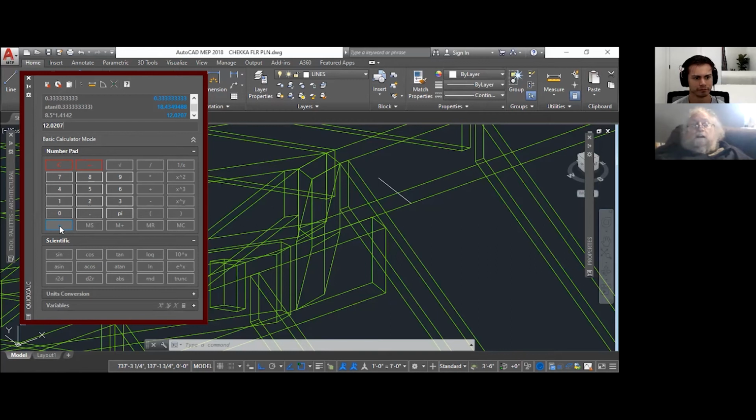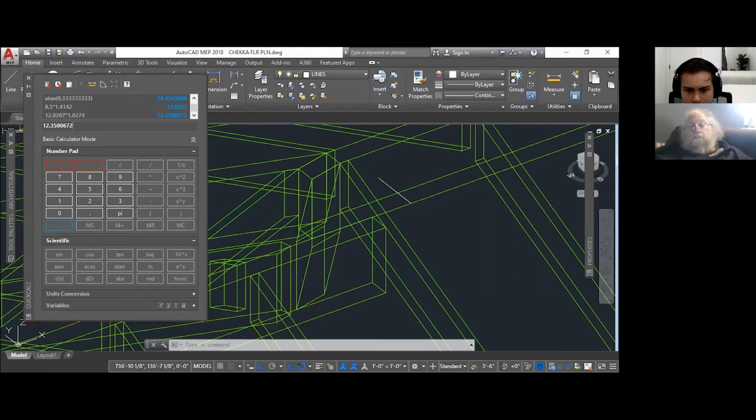Then we multiply it by the secant of the 4 and 16.97, which is what this thing rises at, which I happen to know is 1.0276. That gives 12.74. There you go, 12 3/8. Catch it? 12.350062, close enough.